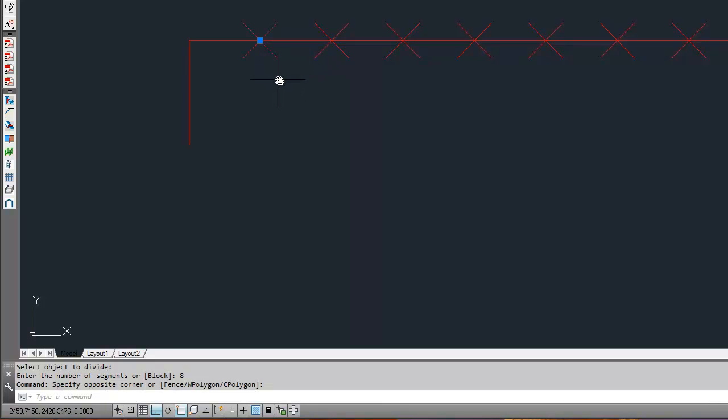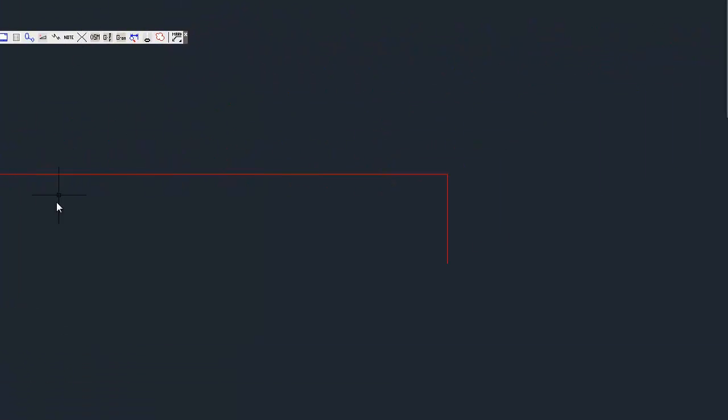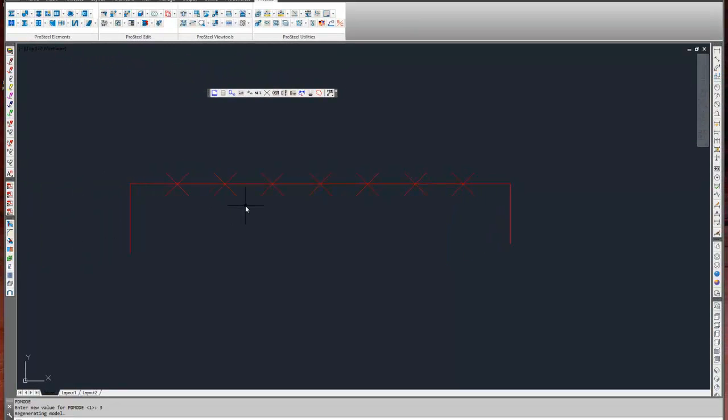Okay, and those little node points can be toggled on and off through this point style change. Okay, so point style 1 is none. If you go enter again and type 3, you get this type. Okay, and you get all different types, so you can have a bit of a play with that. I find this particularly useful because that now gives me something to snap to.